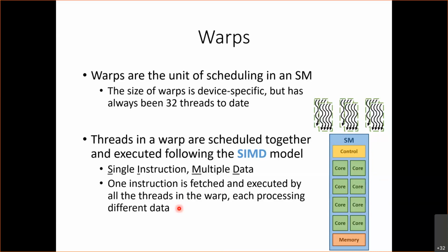And decoding that instruction requires some kind of controller that is looking at the fields of the instruction, figuring out what this instruction is, and telling the different units what to do with it. So if I have a separate instruction decode for every single one of these 1024 threads, I'm going to need a lot of control logic.